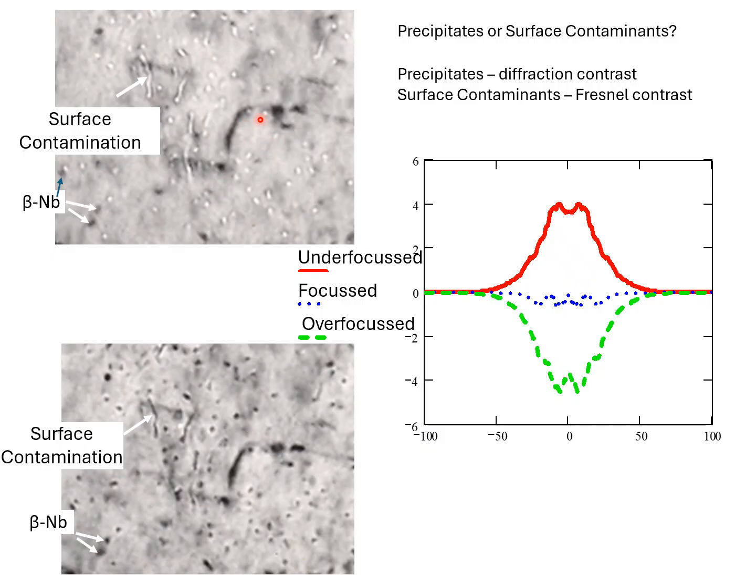This is an irradiated piece of zirconium pressure tubing, and during irradiation, the niobium itself forms clusters, small precipitates, and for whatever reason, let's say I'm interested in these precipitates to know what they are and how they formed.